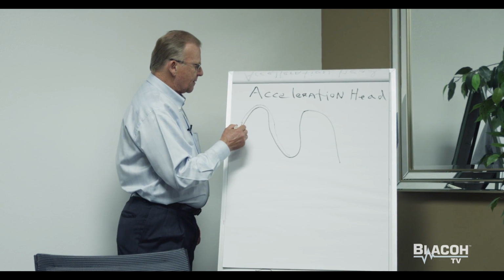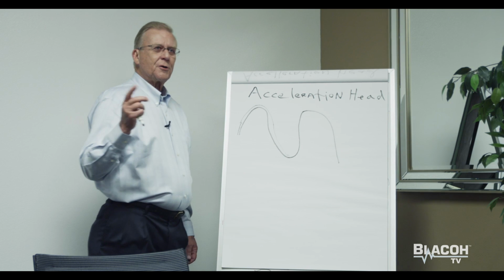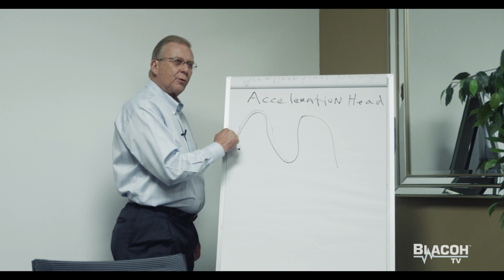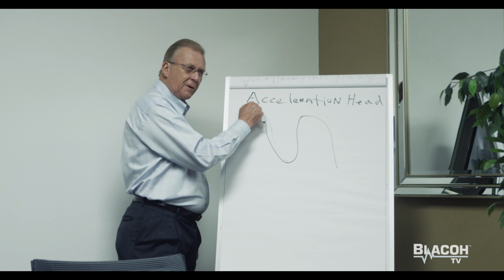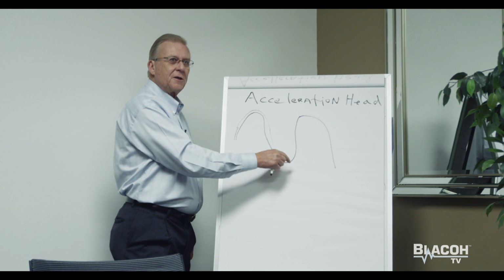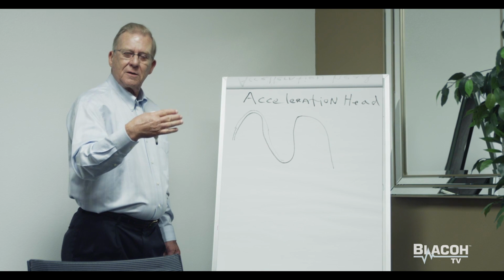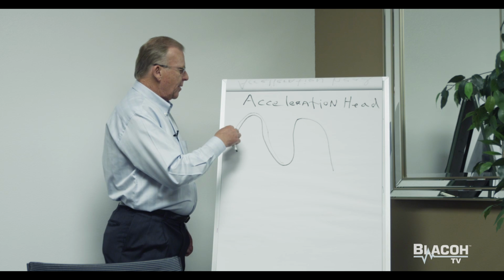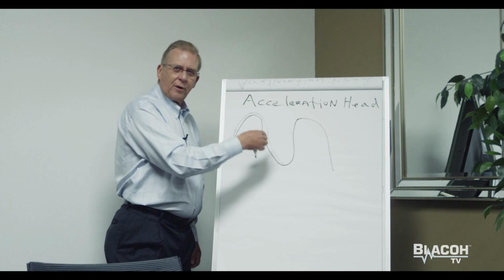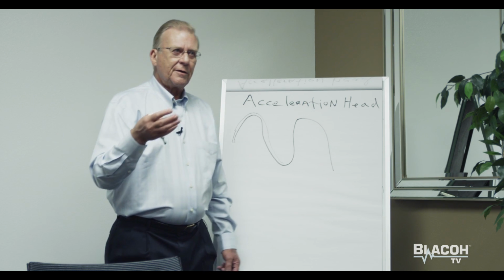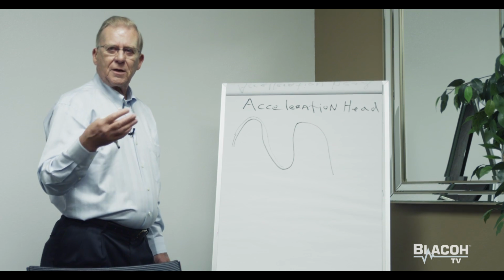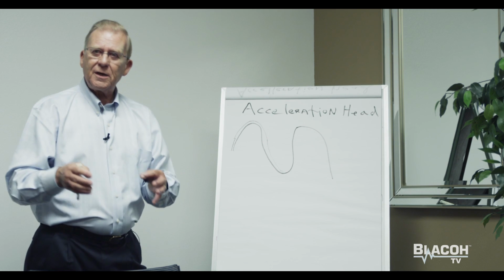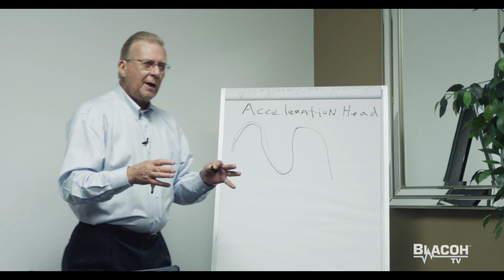Well, this curve is not only a flow curve, but it's a pressure curve, because at the start of the stroke, there's no pressure. Pressure builds to the midpoint and then starts reducing down as the flow decreases through the stroke cycle. Okay? Now, pressure also creates the vibration and other components that occur during the stroke cycle. Vibration, all the other elements. For that pulsation, we use a pulsation dampener.